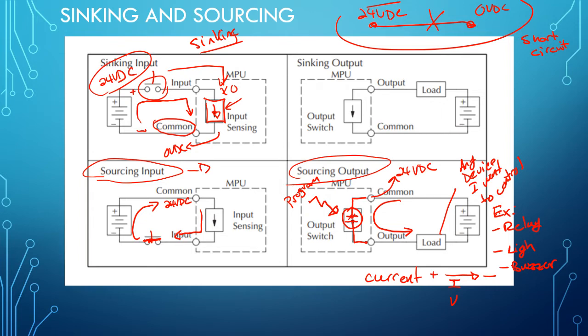Usually, we will not connect motors directly to the PLC because motors draw high current, and on our PLC you will have 24 volts DC available and 0.5 amps per point. So if I were to ask you, Y0, what is the voltage that Y0 can provide, and what is the current? Well, it's going to provide 24 volts DC and at a maximum of 0.5 amps.